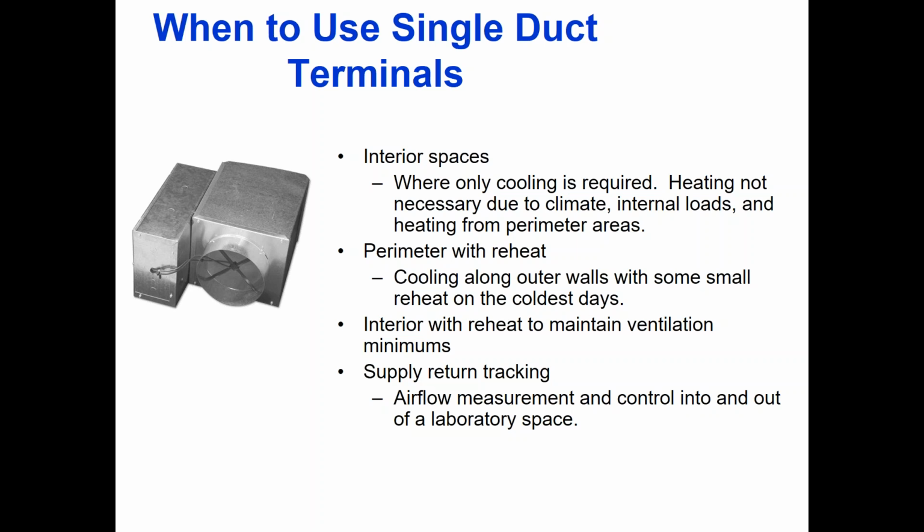It's a pretty low number, but you'll have some minimum pressure. The VAV box cannot operate unless I have a minimum operating pressure coming to it. Otherwise, it's not going to really do anything meaningful.